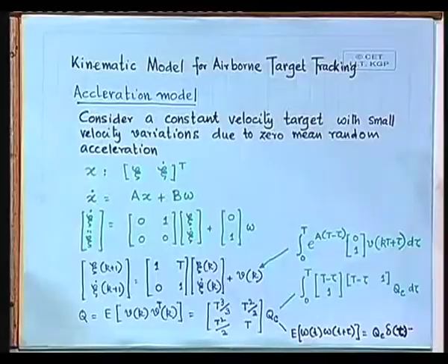Now, it may appear to you that if you have position, you differentiate position and you get velocity, no problem. But it turns out that if you take such a naive approach, you land nowhere. You will get absolutely no estimate of velocity at all if you get a noisy measurement of position and try to directly differentiate it. So you need to do more sophisticated estimation, which is by Kalman filter, and when we see our numerical simulation, this will be borne out.